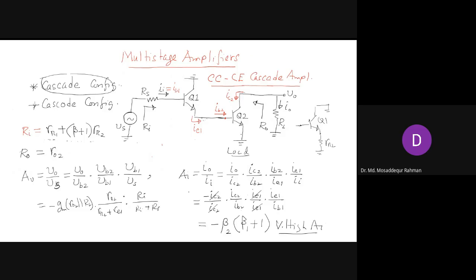And the voltage gain, is there any change in the voltage gain? So this is the gain for the common emitter, and this part we get for the common collector. This is basically almost equal to 1, because the small re is much smaller than R by 2. If you ignore this part, it will be almost equal to 1. So basically it reduces to this part and this part, which are the same as the common emitter.